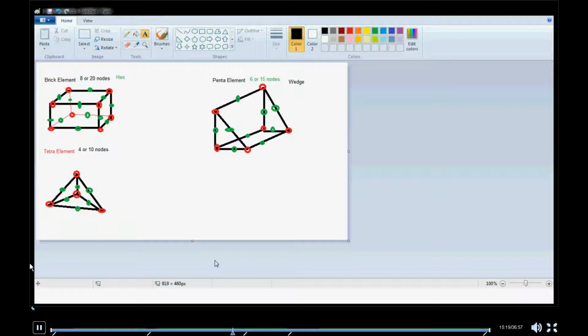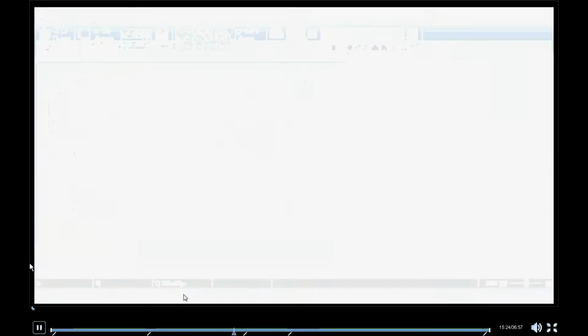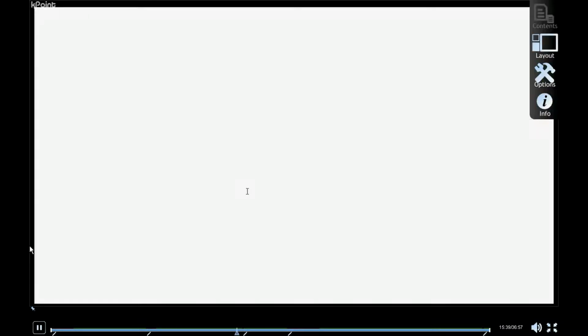So now let's go back to our help and try to see the different elements. What are those? Okay, solid elements. So solid 45, now you know, it's an 8-node brick element, isn't it? Brick kind of shape, but this can also take a penta shape or tetra shape based on the situation or the geometry complexity. Now, then solid 85 is again a brick element with 8 nodes. You can see, again it can take a penta or tet shape.